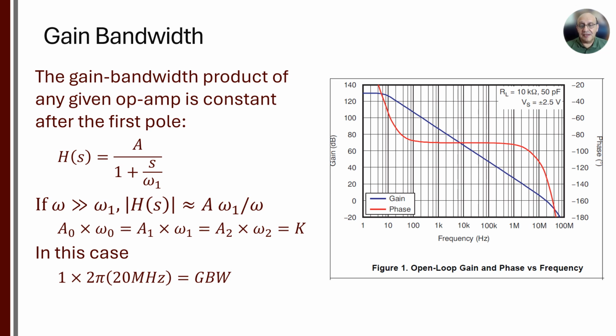What we have is a frequency response, which corresponds to the OPA322 operational amplifier. And we have a dominant pole. This is our dominant pole. All operational amplifiers have a dominant pole. The DC gain, in this case, is 130 dBs, which corresponds roughly to about 3 million. So we have 3 million right there.